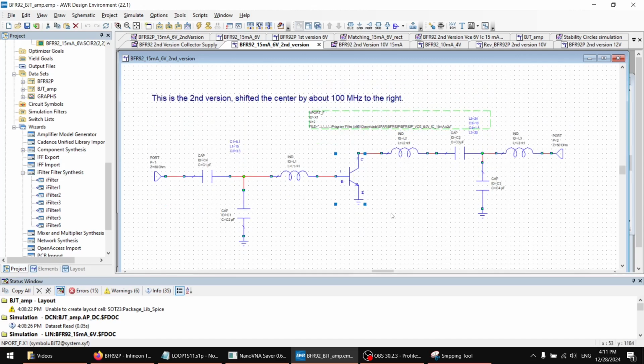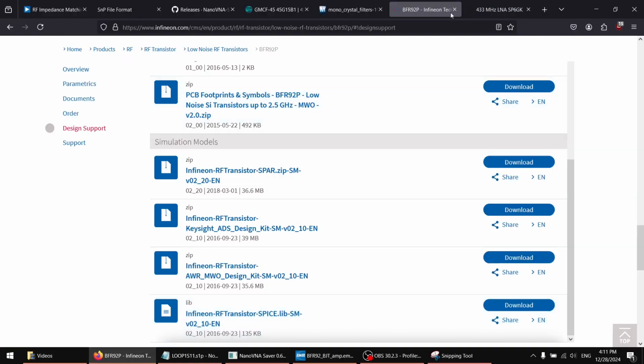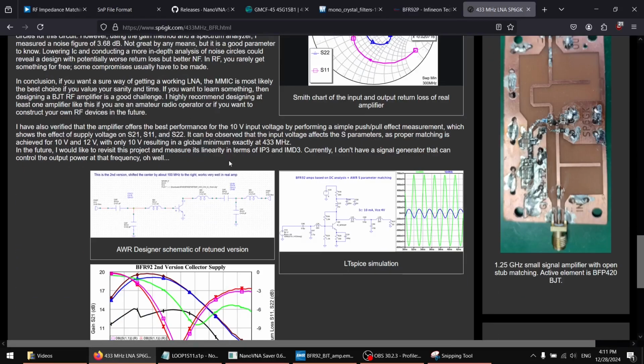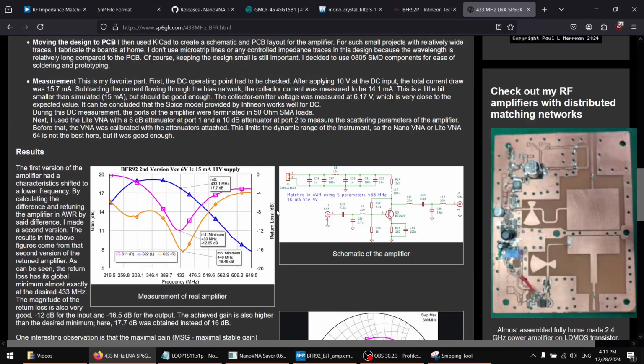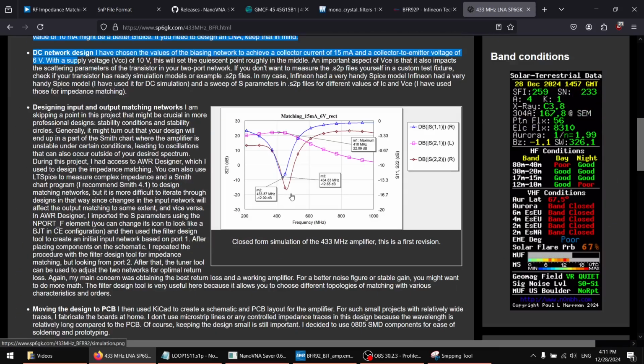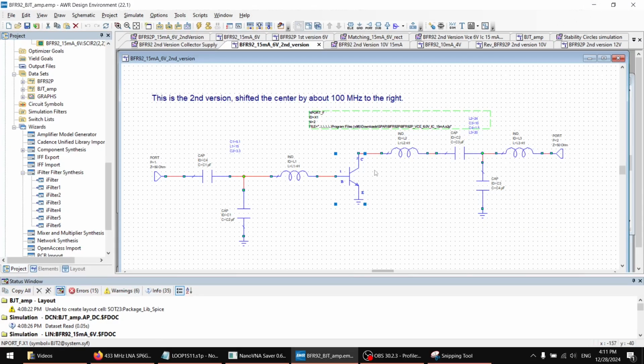And another thing that is important to remember: this is an acceptable method for low signal amplifiers like this LNA that I've designed. If you were designing a power amplifier, for example, this might be more complicated because you would have to use a load pull method, since high power devices will experience more nonlinear effects, and nonlinear methods of load pull are necessary. Load pull is also available in Microwave Office, but it's not part of this tutorial so far.